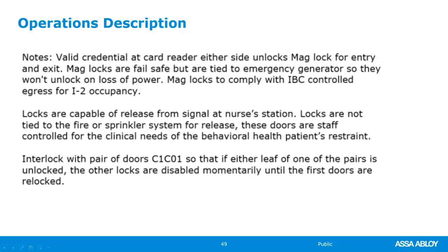The locks are capable of release from signal at nurse's station. So there's one extra layer of safety. The nurse's station can unlock those doors. Locks are not tied to the fire or sprinkler system for release. These doors are staff controlled for the clinical needs of the behavioral health patient's restraint. That is phrased and put that way because that is exactly how the exception reads in the IBC.